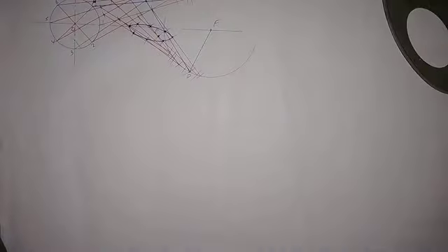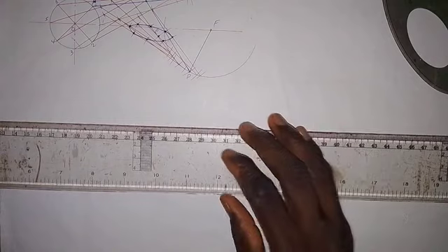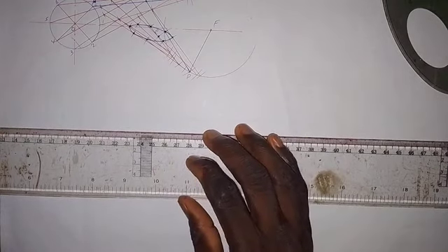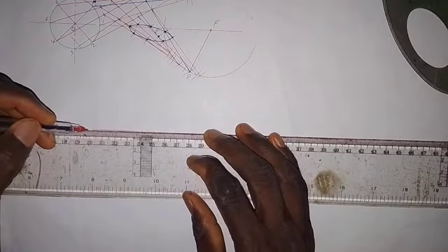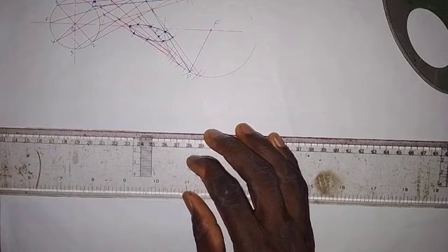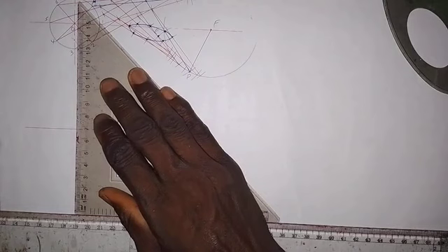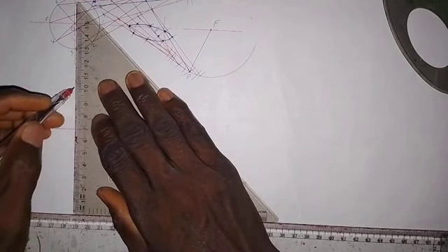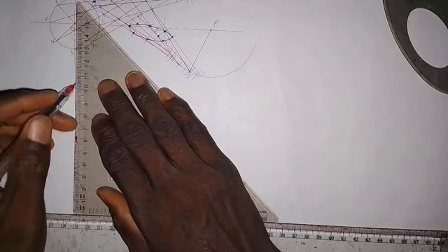So we are going to put all these dimensions together to obtain the locus of point B as we are instructed. The first thing that we need to do is to draw a short horizontal center line like this. Then we draw a vertical center line.